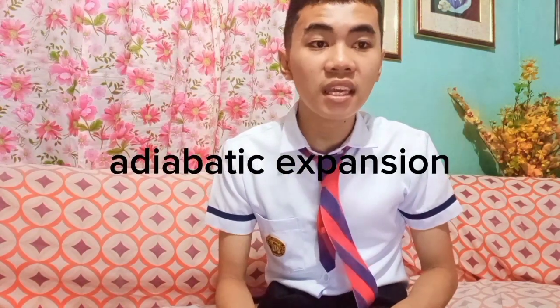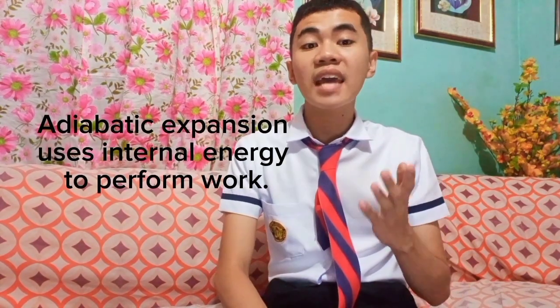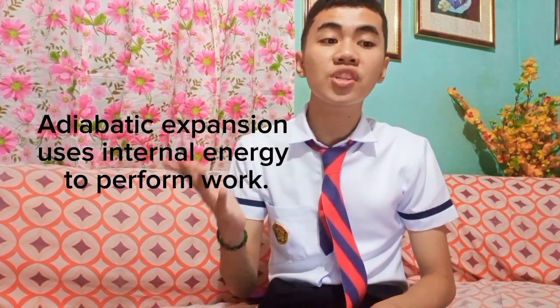So we've already talked about the reversible adiabatic process and the irreversible adiabatic process, but now I'm going to talk about what is an adiabatic expansion. The adiabatic expansion is defined as the expansion in which there is no heat interaction of the system with the surroundings and work is done by the system at the expense of its internal energy.